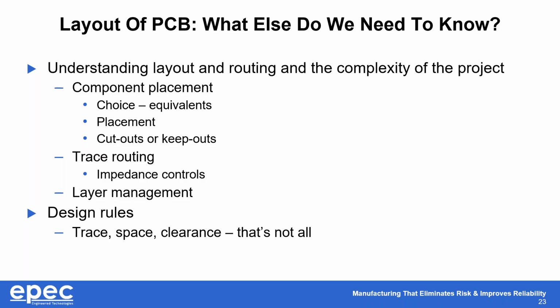Trace routing and your impedance controls, if you can call those out on your schematic as a side note, that's good for us as well. Your design rules, trace and space clearance, that's not always up to you, sometimes driven by the components. We'll work with you on some of that if we need to make any tweaks or changes to it. But if you know anything that we should know up front, please give us that information as well.